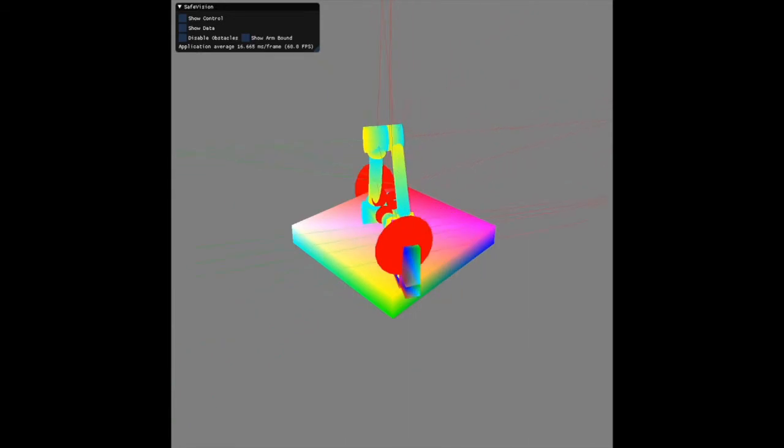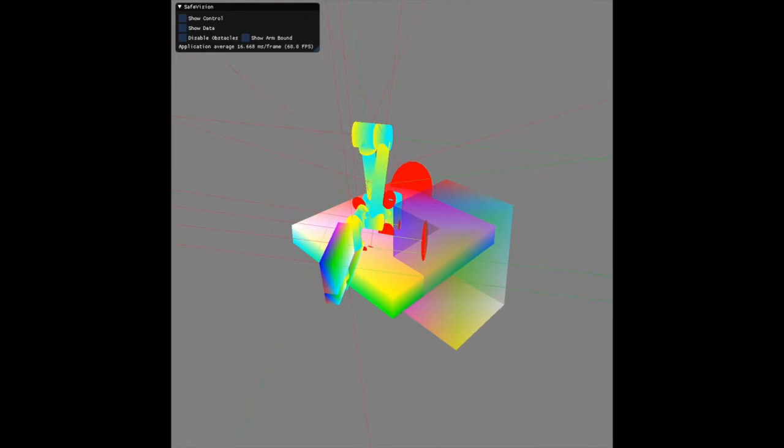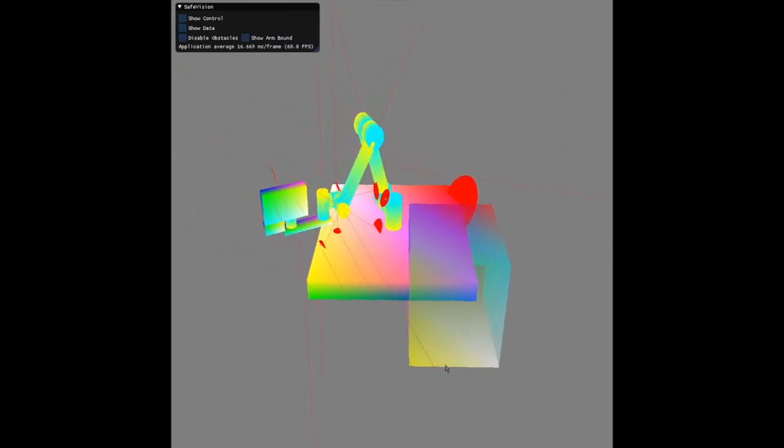Each situation test has 3 steps. First, the arm moves to its starting position. Then, obstacles are placed in the simulation, and finally, the arm moves to its end position and may or may not stop. In the test just shown, the arm correctly stopped because a sensor near the head of the arm detected a nearby obstacle. In this next test, the arm starts very close to an obstacle. However, because the arm moves away from the obstacle and isn't in danger of colliding, the arm doesn't stop.